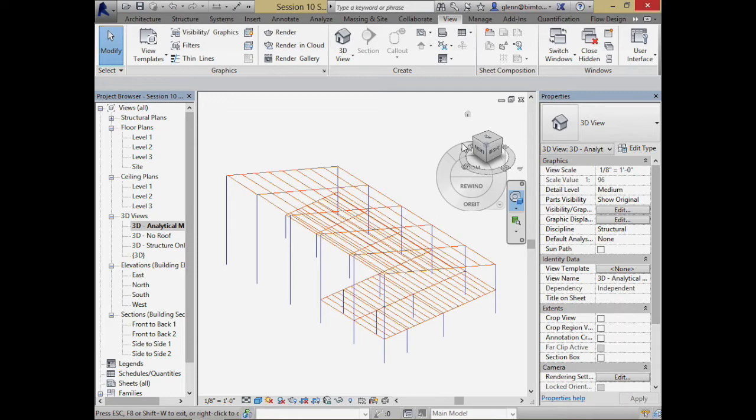And this will determine, on this big plane of the roof, what's supporting it in the end and what it's all connected to. So don't get worried if somehow the physical model looks a little wonky. If the analytical model is correct, then things are supported the way they need to be, and we can clean up the physical model as need be to make it look better.